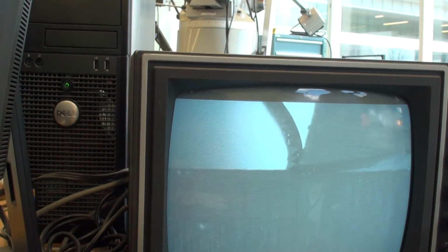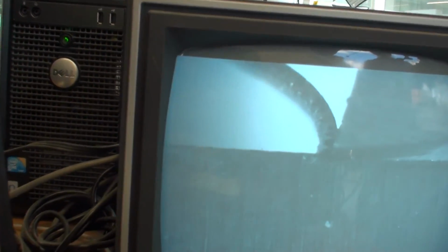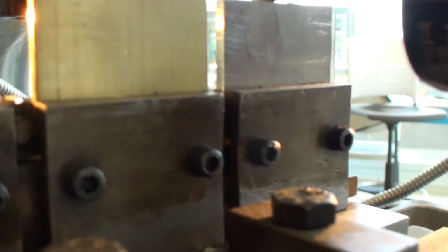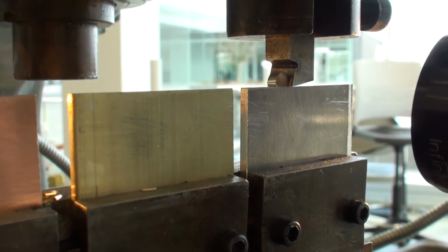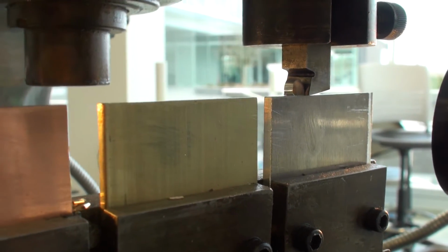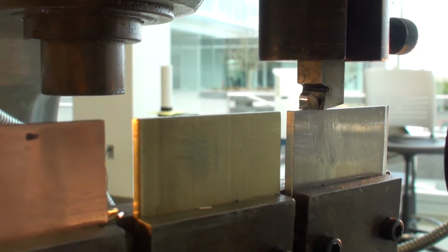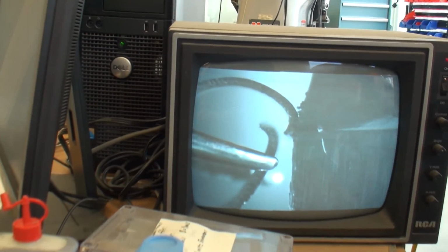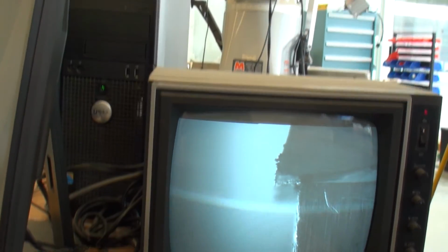And notice on our screen here, we have a pretty straight chip coming with our piece of aluminum. And here's what this is looking like in real time rather than amplified by the video camera. About 2/3 of the way across, our chip is now finally starting to curl. Alright, so we're going to capture these chips and we're going to run this for all 3 materials, and we'll be back to you shortly with our chip thickness readings.